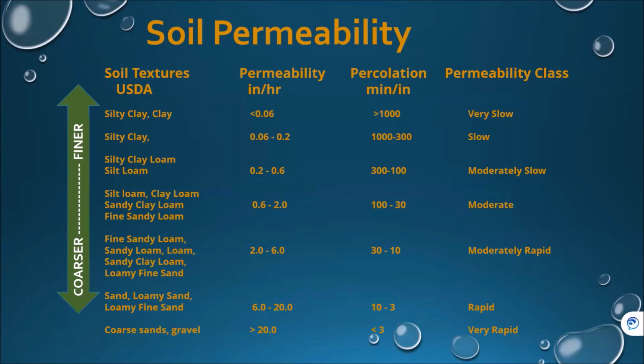So, soil permeability is pretty directly related to the soil textures that we're going to find. Why do we care about soil permeability? Well, if we've got an area where we want to hold water, we want to keep it there as long as possible. Hopefully we don't lose it all out the bottom through a really sandy site. Or do we have enough material above it that will hold, or that we can at least manipulate so that it'll hold that water and provide the wetland benefits we're trying to achieve on the site?